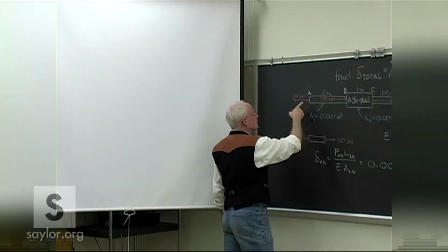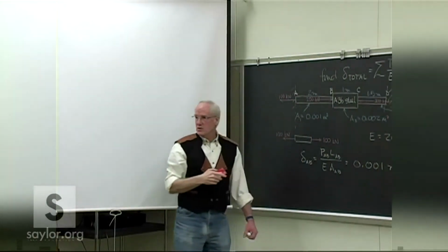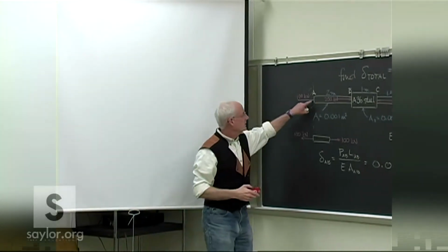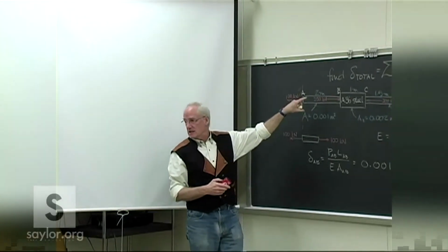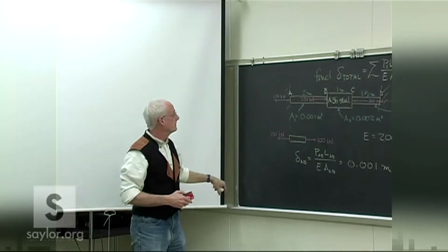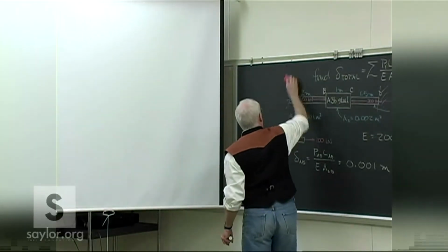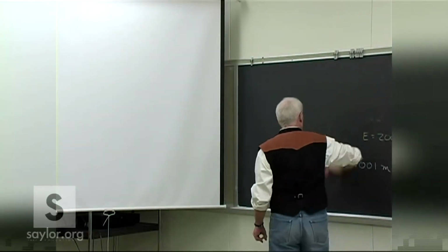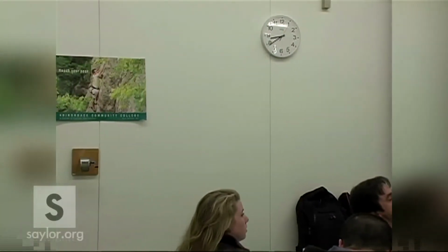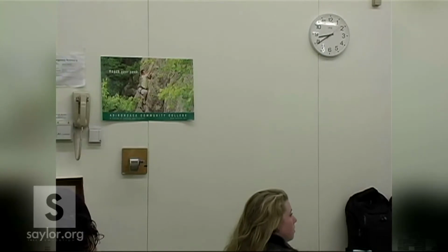We're going to look, starting tomorrow, at just what to do when we do have this kind of constraint on the piece itself. Because this is statically indeterminate. We cannot solve this problem with the straight statics that we have so far up here. We're going to have to bring into it this deformation of the material itself. But it makes for a pretty interesting problem when we get there. Sounds like you might need to apply linear equations. No, not on this. Okay. Well, yeah, if you're talking about you'll have a system of equations that need solving, yeah. But they are linear.